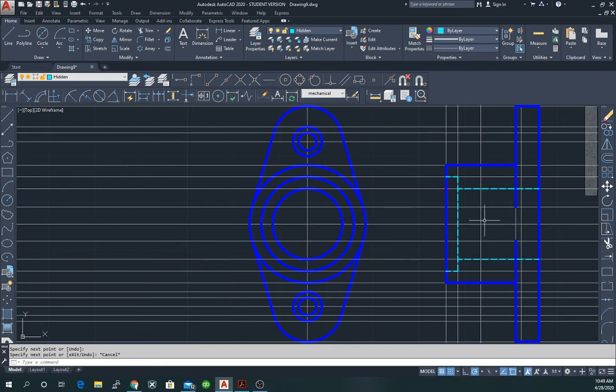While we're here, there's a hidden hole that we can't see, of diameter 0.375. It's located 1.25 inches out, and that's why we put this line in. We'll click here, type 0.375. That takes care of that hole.